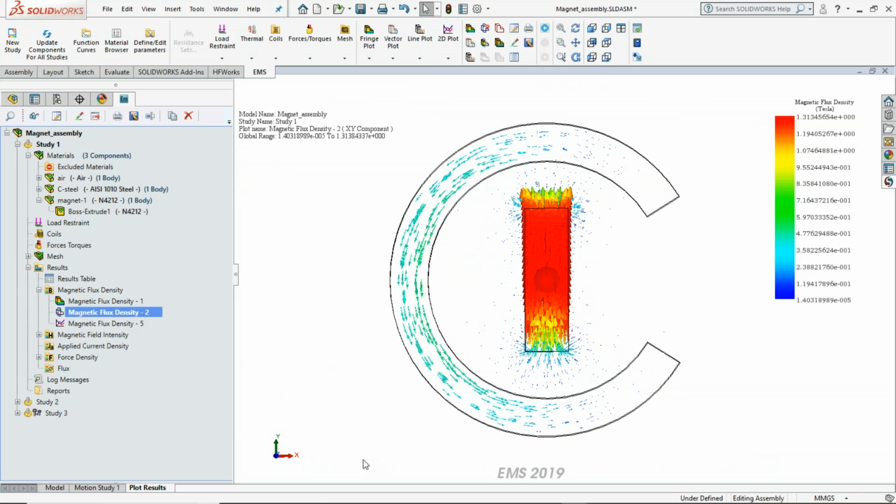The magnet is aligned along the y-axis of the assembly where the angle between the two planes is 0, and you can see how the magnetic flux lines are distributed as vectors. So the problem is interesting because now I can vary the angle of the magnet as a parameter, and I can study how it impacts the magnetic flux at a particular location.